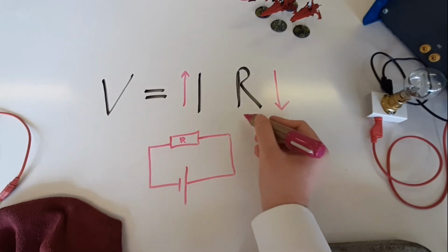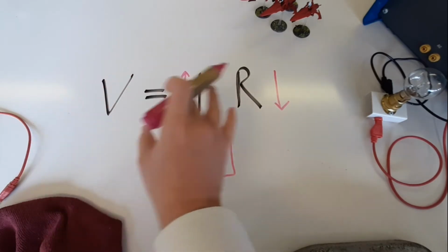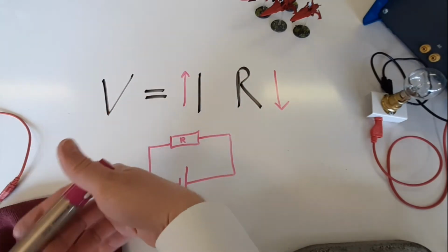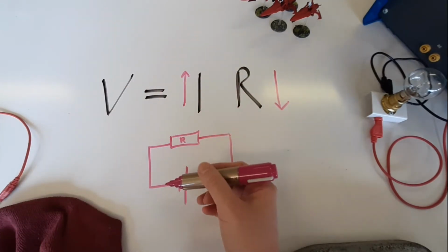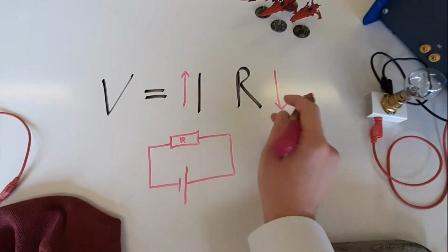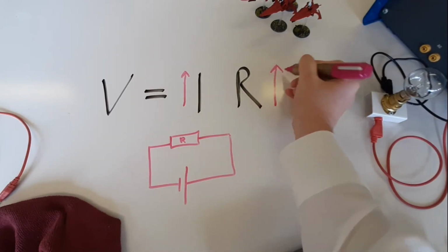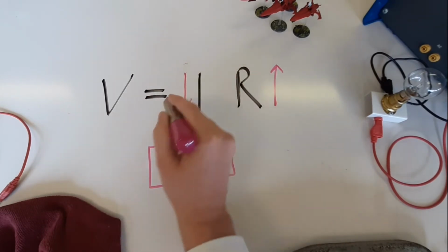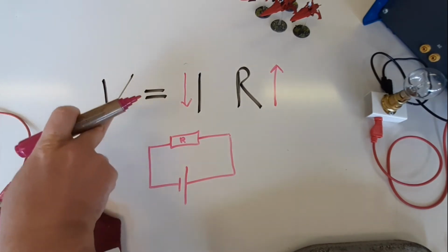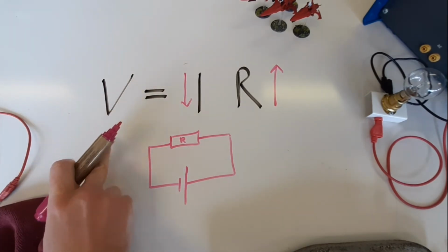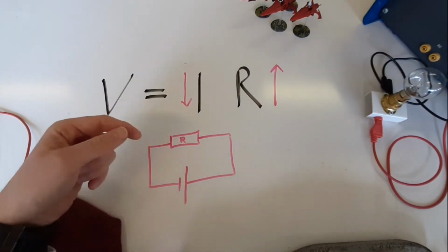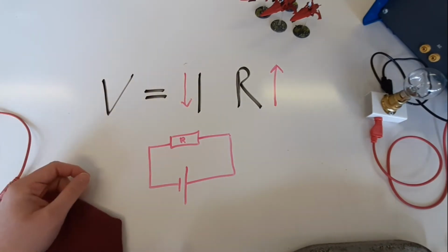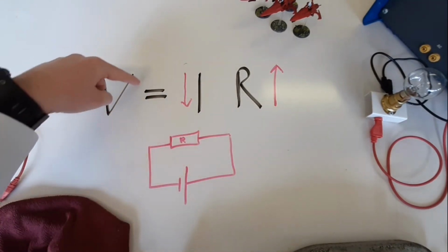If we make our resistance effectively 0, then assuming we had the same voltage, okay, can't actually do this one because then you divide by 0, but there we go. The current would effectively go up to stupidly high rates and you'd probably end up with a fire and stuff. So there we go. Now, flip side of that though, if we increase the resistance, basically made it more difficult for the current to flow, then of course the current's going to go down, provided we keep the voltage the same. And that's the idea. If we increase or lower the resistance, our current is going to do the reverse of that, which means it goes up and down depending on the resistance there. Provided you keep the voltage the same.